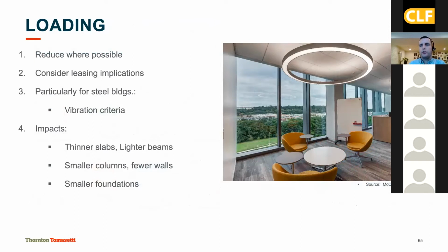And then as a structural engineer, I'm always worried about loading and what loads to use, what's required by code versus what is common in the region, what's demanded by the owner, what's expected by tenants. Recently in the DC region, we've seen a push on retail establishments. Retail tenants want 125 pound per square foot live load, not 100. Maybe they're asking for 150. Those kinds of decisions, 125 PSF live load versus 100, might mean an inch on your slabs.